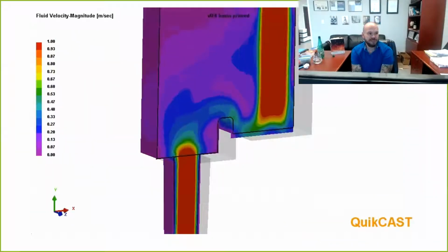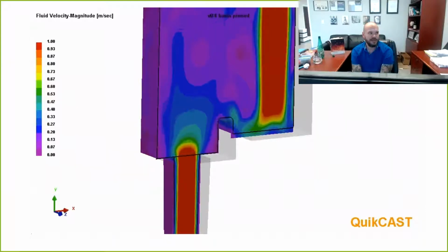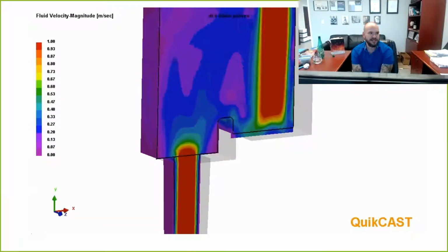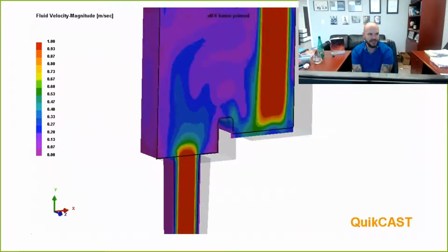Here's a computer simulation showing exactly what we were just talking about. So this is in a fully primed basin. The color gradient that you're looking at is velocity. And you can see that what we're doing is we're arresting and separating that velocity component and restarting it again at the sprue entrance. This gives us, again, perfect control and design of our fill system, prevention of the aspiration mechanism, and an opportunity for detrainment.